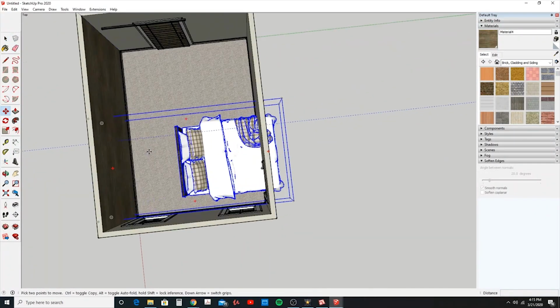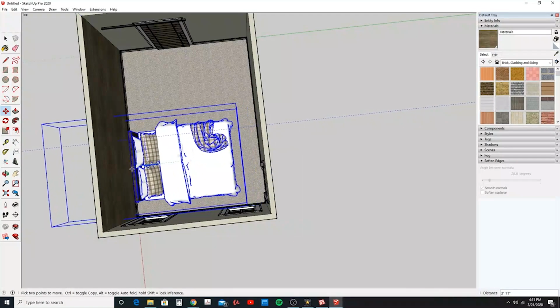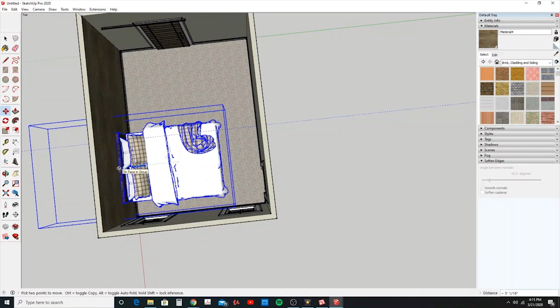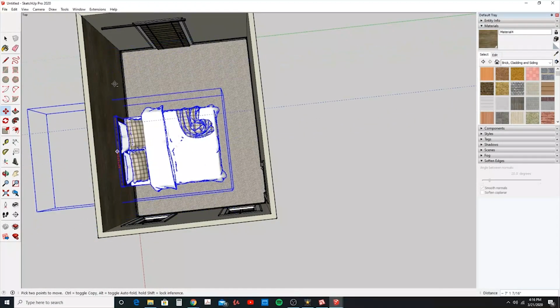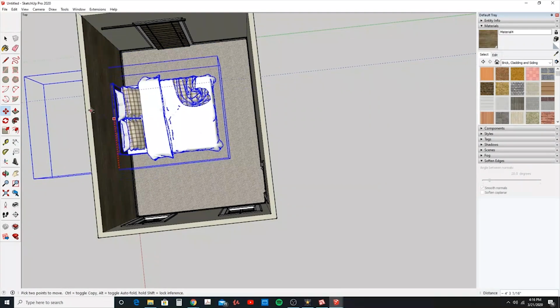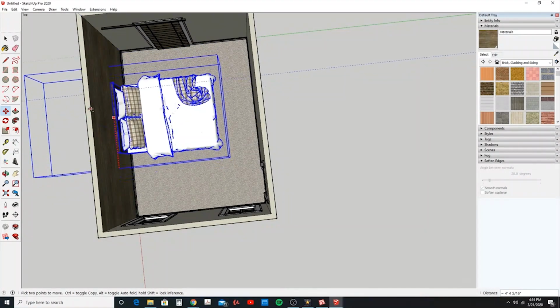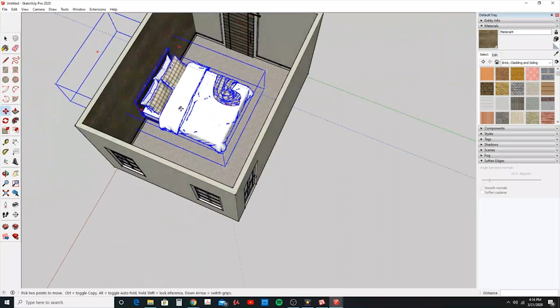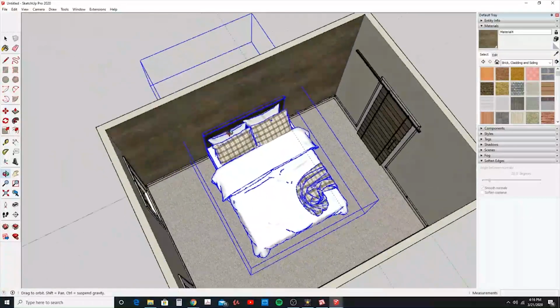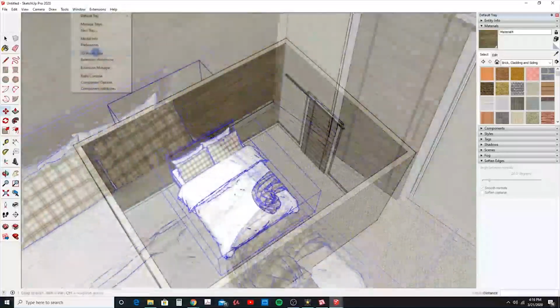And let's go ahead and move it against this wall. And there it says it hits the face of the group. And to center this wall, here's another trick that I'll show you. Here we have selected the center, and I can use the arrow keys to lock the movement along a certain axis. So here I'm aligning it up with that midpoint, and there I placed it exactly in the center of that wall.